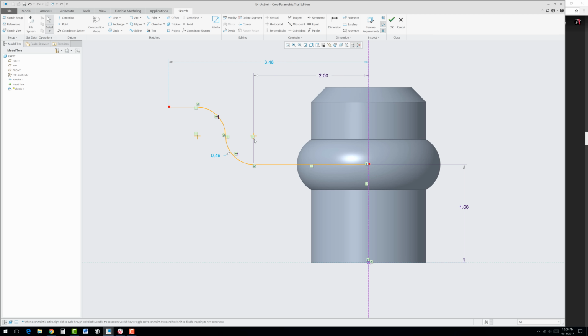Okay, now we can actually see what's going to happen with our option there where we added this constraint, which essentially gave us 90 degrees, but it's a horizontal alignment. That's probably going to be some trouble later on if we try and change this, but let's first make this 4 inches wide. Okay, now these should be 1 inch. And you'll notice you can't change it sometimes. If you double click, try and change it to 1, you may not be able to change it unless you made it extremely large to begin with. And this is due to this constraint that we got by accident.